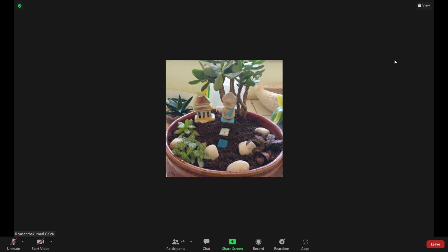You see that there is a gap provided in the ring. Why is that gap provided? We know that when metals get heated up, they expand. I think you have studied this in heat transfer. This is because of the linear coefficient of expansion.